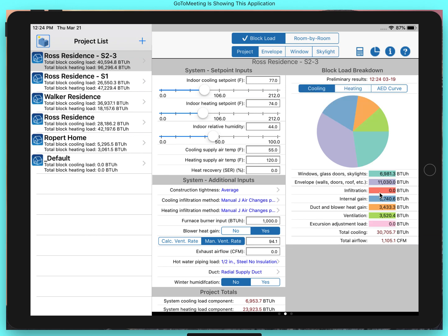And then click done, and you'll see here's my, let's go here. Actually, oh, there's no infiltration. I think the reason there's no infiltration is because I have ventilation. And what's happening is because I have outside air coming in through my furnace, it's actually causing a positive pressure. As a result, there will be no infiltration. But if I did have infiltration, it would fill it out here.